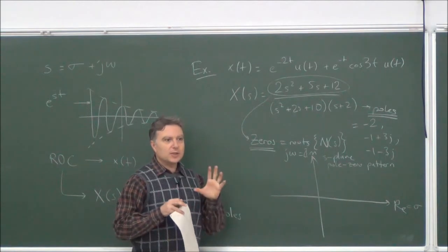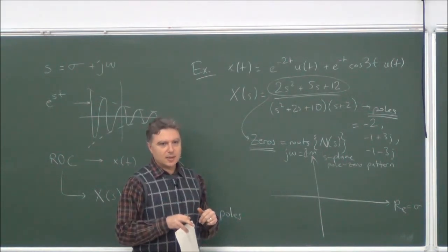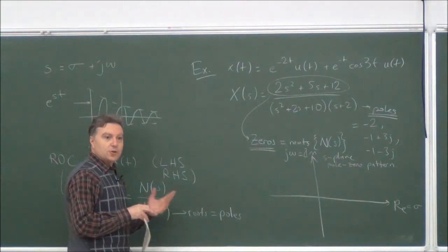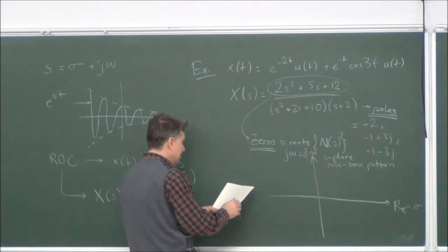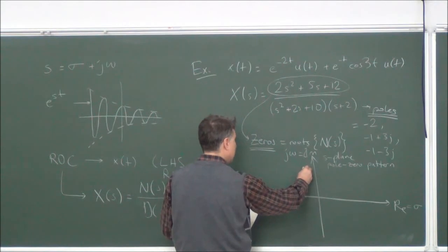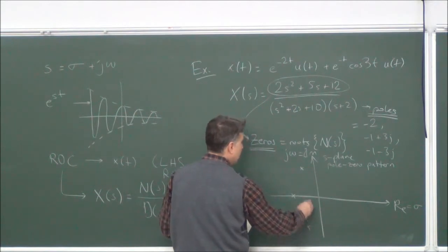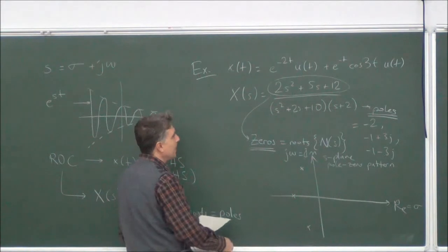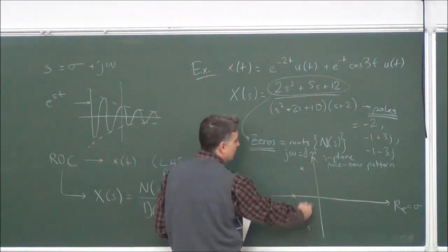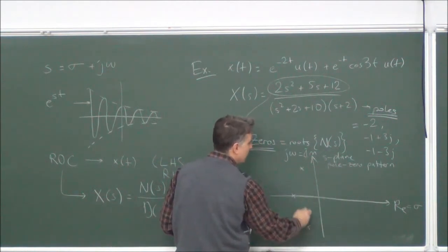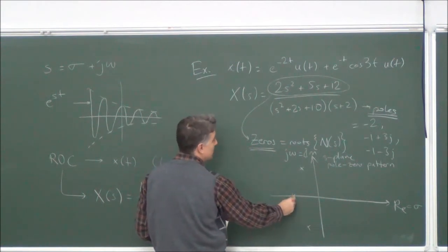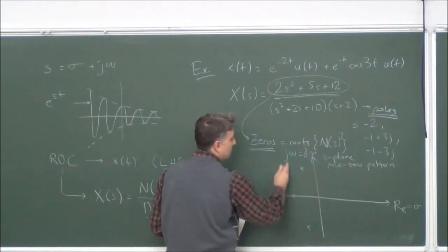And all you have to do is to indicate poles and the zeros on this plane, and indicate the region of convergence as well. Now, as we already know, the poles are very important. For example, for this question, the poles were like this one. And since the whole system is right-hand sided, it is to the right of the real part of these two poles, which is the same, greater than -1, and the intersection with to the right of -2, coming from this root.